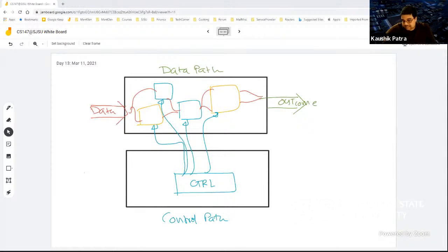Then we'll design the J-type. And at the end of the day, we merge the R-type, I-type, and J-type data paths together on top of each other. Again, we look at the different incoming data conflicts and start placing multiplexers on those to resolve those conflict points. So at the end, you'll see we actually end up using a bunch of multiplexers throughout the whole design process, and that's kind of the backbone of the processor design. All right, so question.